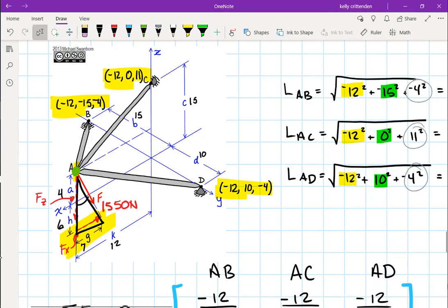So, you know, if you're hanging from this set of bars and you can visualize how they're arranged, then this one is going to be in tension because you're kind of pulling it apart. It's bolted up here and you're pulling down here, so you're kind of pulling on the edge. These two, they're tilted up a little bit. It's hard to see, but they're tilted up a little bit. And when I pull down, these two want to go into compression.